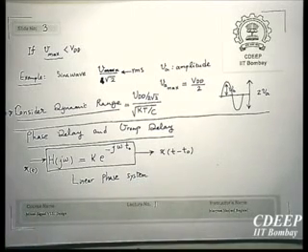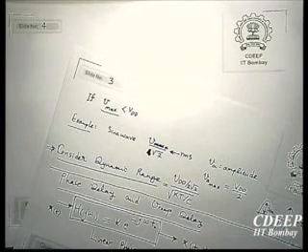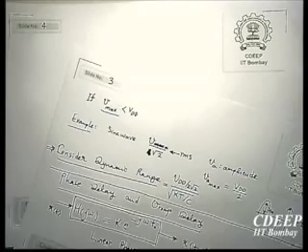So therefore, if you want to have a good group delay, this simple example says that you should try to keep the phase of the transfer function of the system as linear as possible. If it is linear, then it is much more likely to get a delay which is almost the same for all frequency components which are in band. Now, it is not possible to really design all filters with this characteristic.